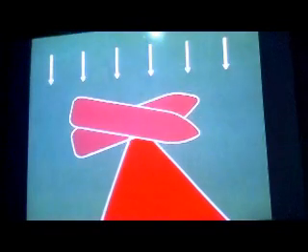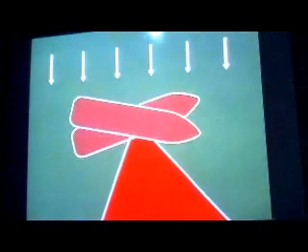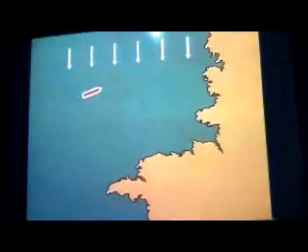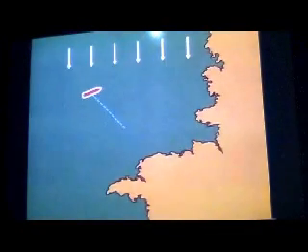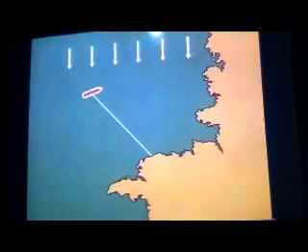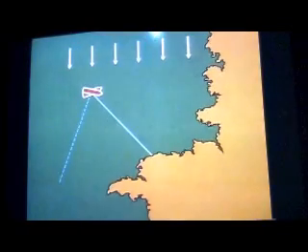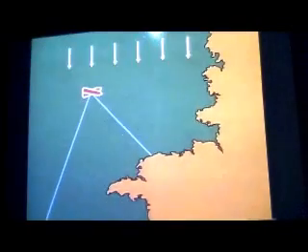The equilibrium condition is not always stable, however, and a vessel's heading may suddenly change without obvious cause. And so, knowing whether your vessel drifts with headway or sternway is vital. For if engine failure, for example, occurred to windward of a headland, the head may be allowed to pay off, and the vessel sailed safely out of danger. The red area shows the possible drift sector of this headland.